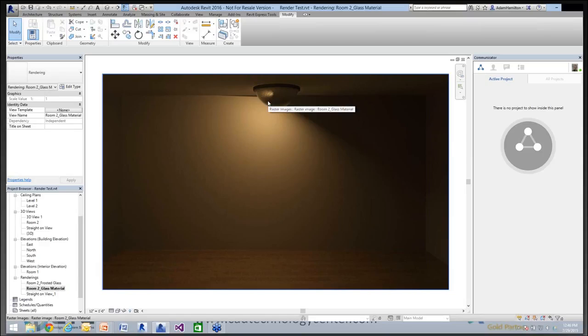But Revit objects do not glow due to lighting. Lighting does not diffuse into a lampshade or a globe or a light bulb. The light object, the yellow symbol, does not illuminate materials. Thus, the globe of this light is a frequent issue that a lot of people have: hey, my light doesn't even look like it's on. My room is lit, but the light is not on.